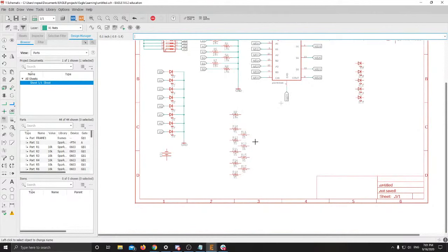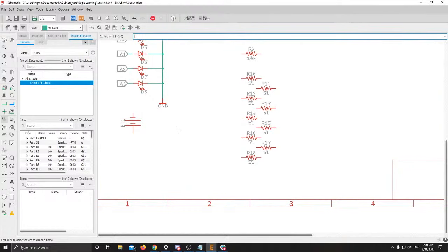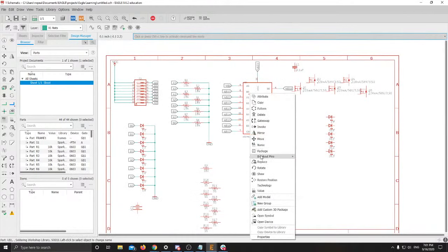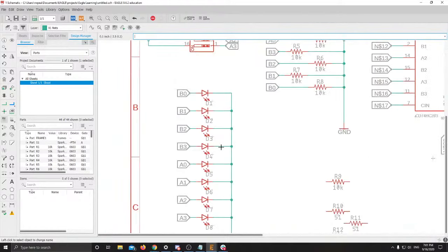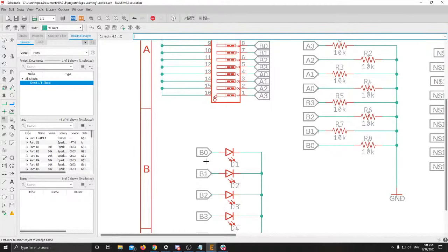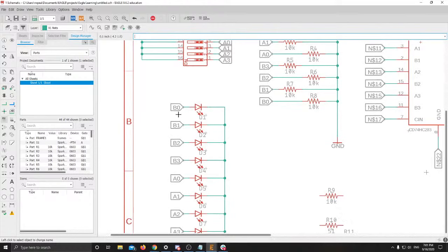So since I have my resistors, sorry, there's a quick question in Discord that I'll answer. Can you put a label direction on the part without first adding a net? So no, you can't, unless you do that thing that I showed on the IC where you right click, breakout pins, all pins, and default. The issue is that Eagle doesn't actually make a connection to this end until you add a net. Nets are how it actually references between parts, so you essentially have to add the little stub first.